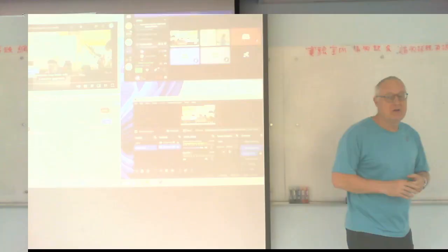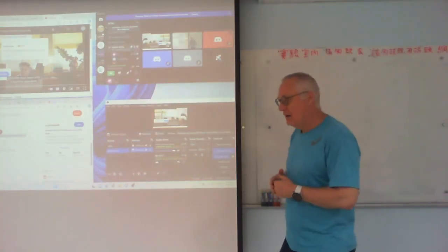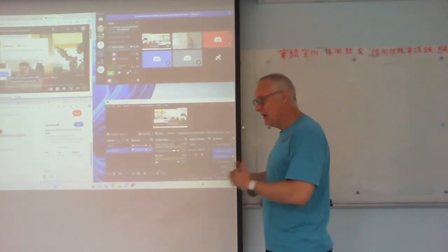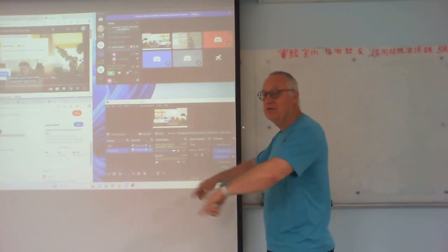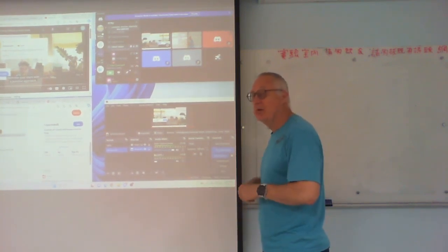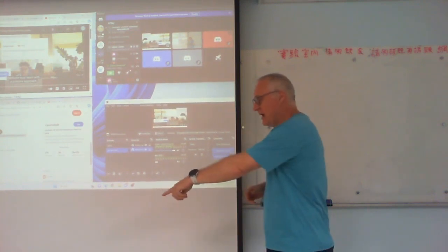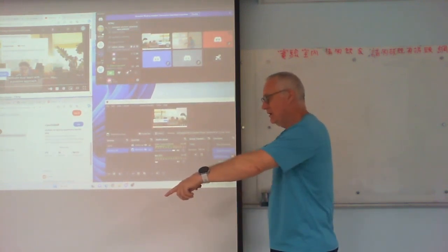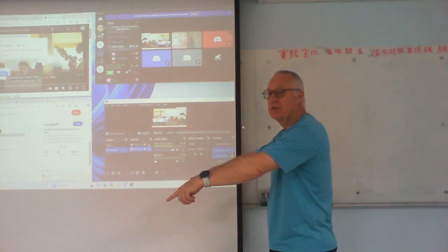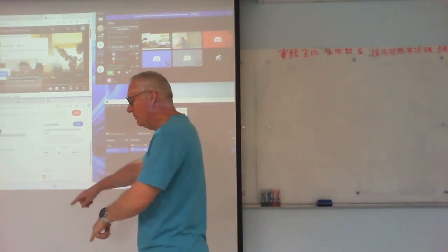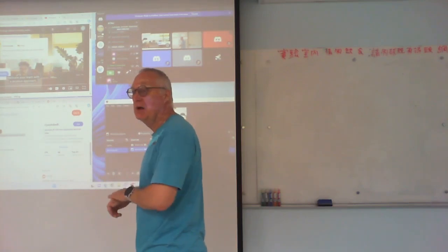So, position is really difficult. But you can also see that if I have a calibrated camera and I can measure distances to points, at least from my local point of view of the robot, then if I can track those two corners of the tiles, and I can see them move, I can now measure my distance to those two places.